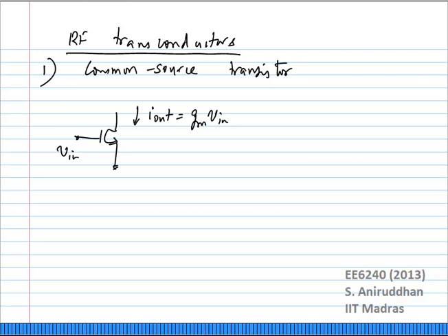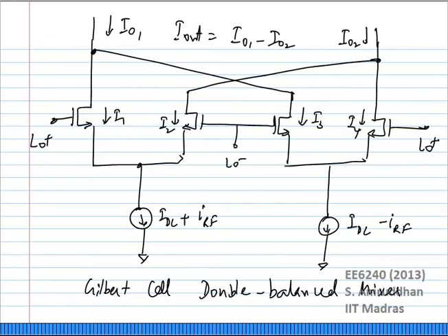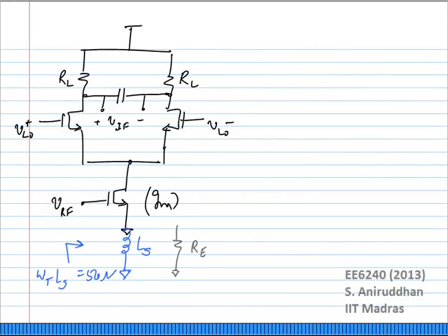No, that is not what I am looking for. You are interested in IIP3. You are interested in Gm3, which we have seen before, at a given VDS. Is VDS fixed? So let us go back to our single balance mixer. Is the VDS of this device fixed?